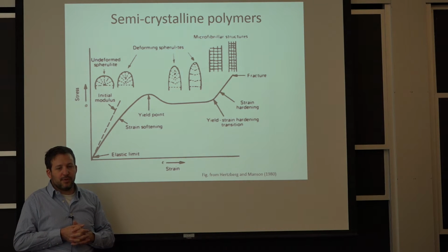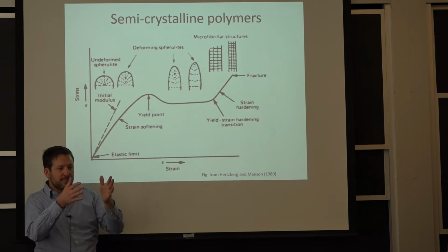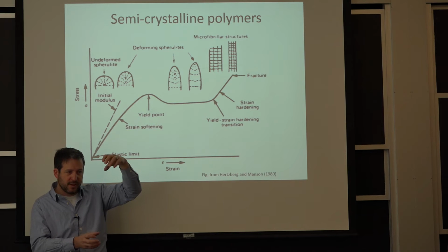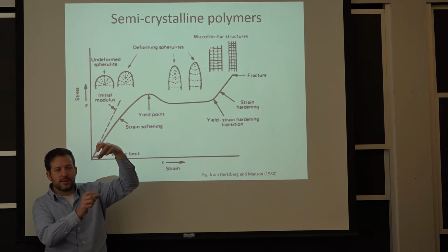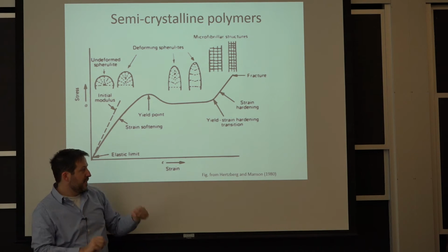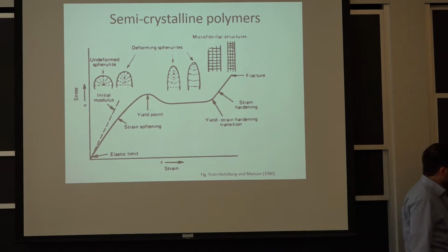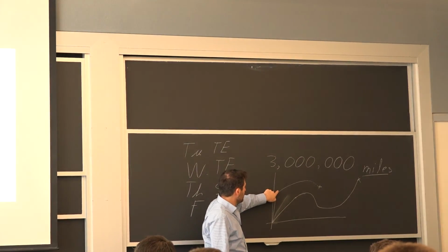When you're not stable against, because when you deform a specimen that's just perfectly flat, you just have the possibility for perturbation. So there's a little bit of an area that gets stretched a little bit more, and therefore the cross section is less, the stress is higher. But what happens initially in this curve for steel is you work harden.